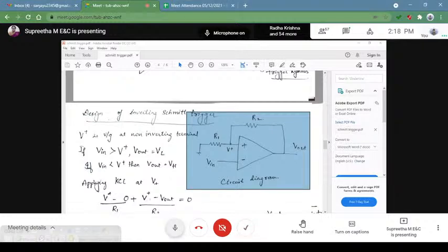V1 is the voltage where your output changes from low to high. So when your output changes from low to high, we're at input V1. I can also call this V1 input my upper threshold voltage, that is your VUT. So VUT is equal to R1 divided by R1 plus R2 into VH, and I call this an equation.